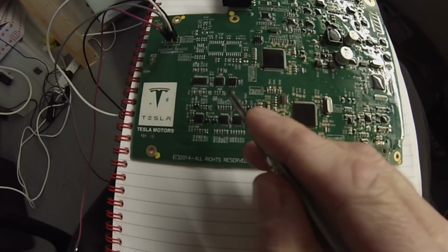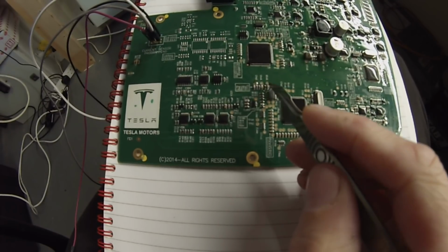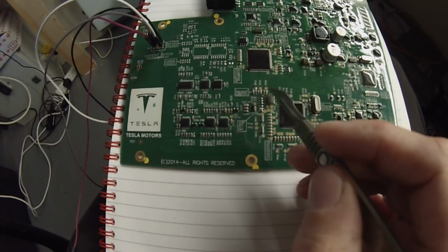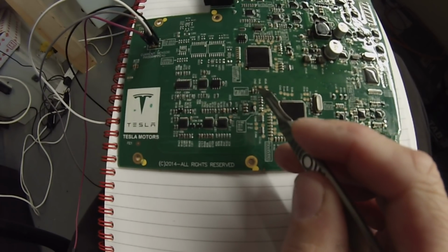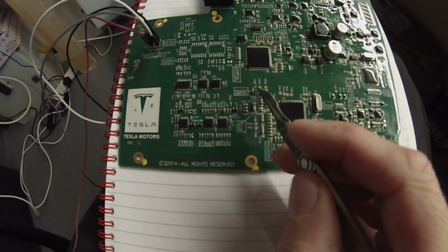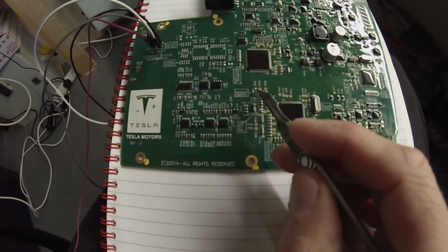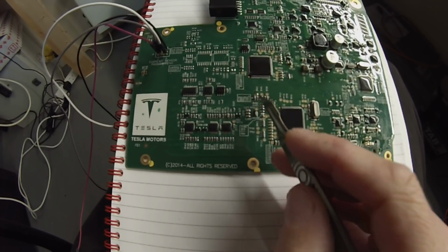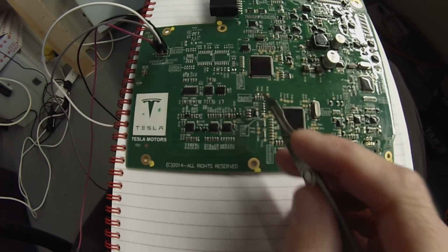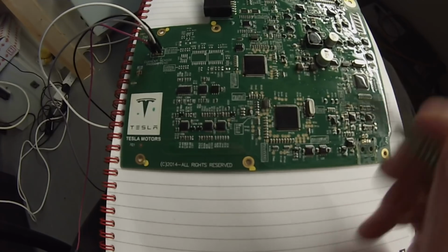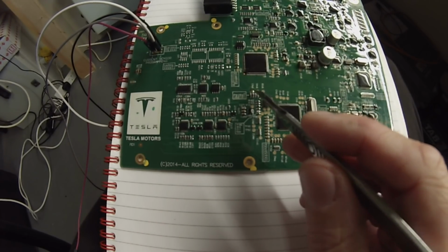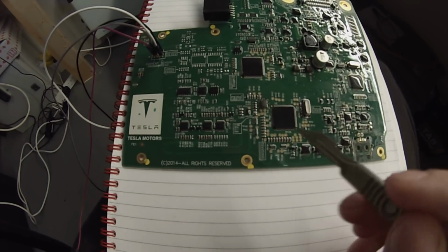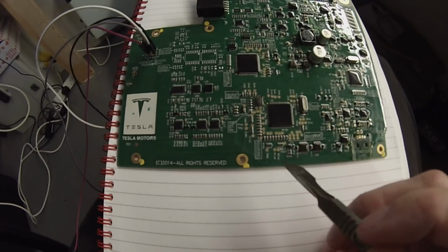I'm going to come over here to these three test points. There's TP43, TP45 and TP58. These are nominally 3.3 volts when our current sensor is within the window. When we go outside the window, these trip low, just like the open source board. They're basically fed to this TMS320 DSP chip. Now what it does after that, I haven't been too worried about.